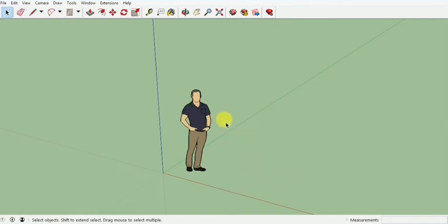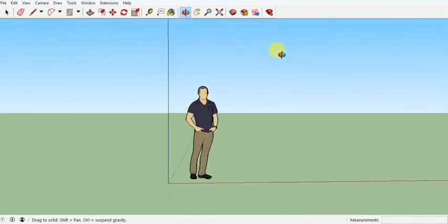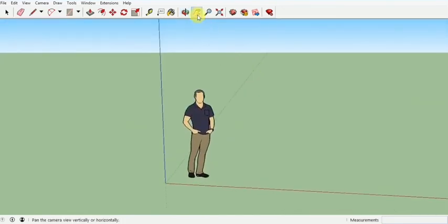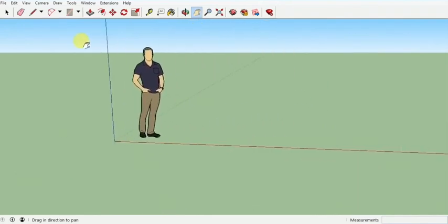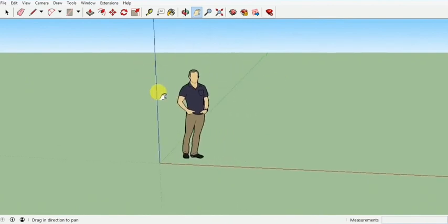So this is basically how do you move around in SketchUp. I would like you guys to just go around, move around, use these commands. So we'll be zooming in, zooming out, orbit, pan, and all of that as well. Now the shortcuts of orbit and pan is basically from here, so you can click on this and just use your left click to actually orbit around if you really want a very basic way to do it. And similar for the pan, we can select this and we can pan around. I prefer using the mouse and the keyboard together because it builds efficiency and it makes us work faster rather than continuously changing to the shortcuts, but you guys can use it as you prefer.